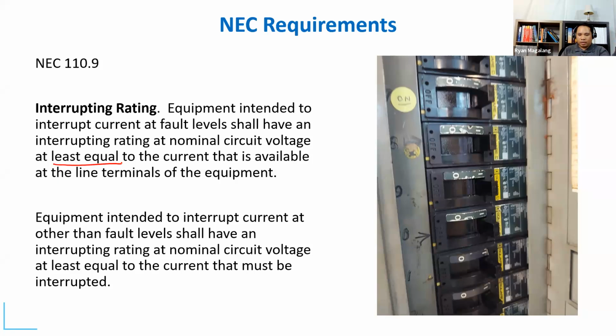It did not say conduct a short circuit analysis, but in order to know the fault current level at that equipment, let's say a panel board, you'll have to conduct short circuit analysis. So it's implied, even though it's not directly being said, that we have to conduct short circuit analysis.